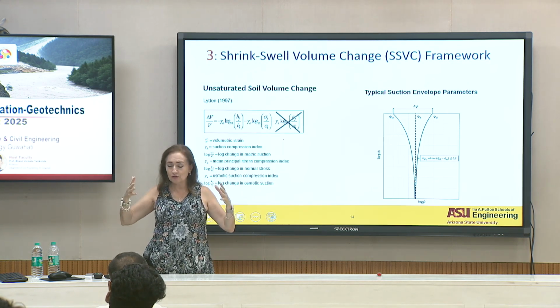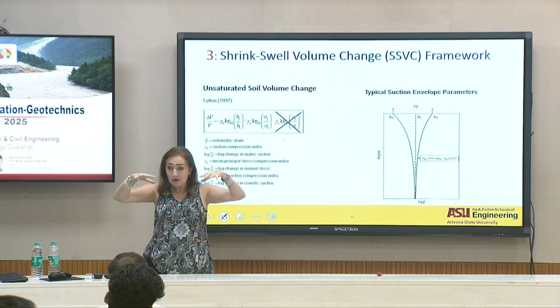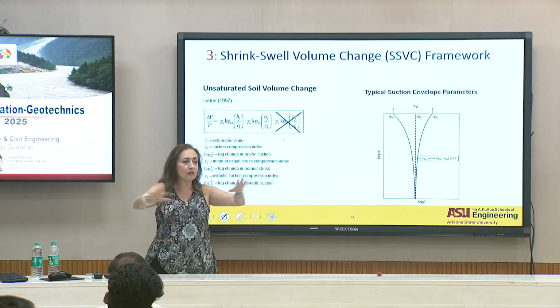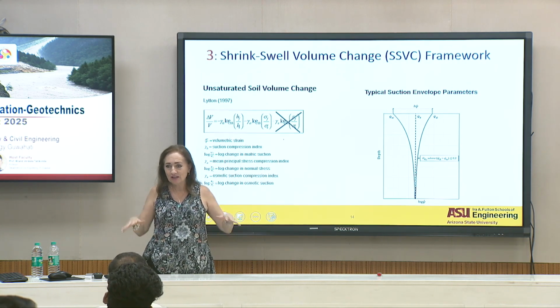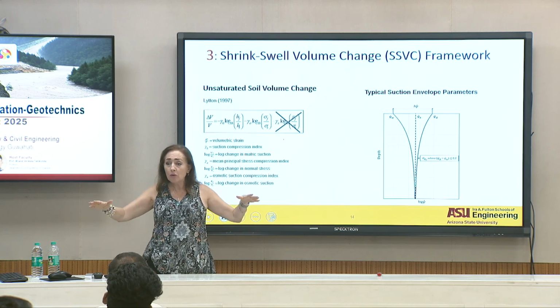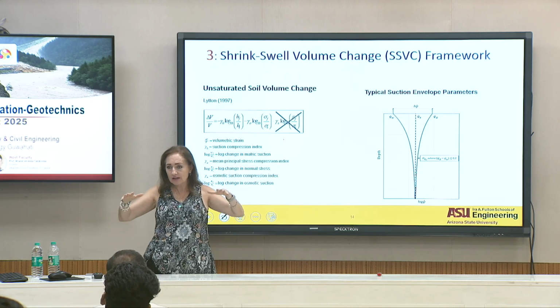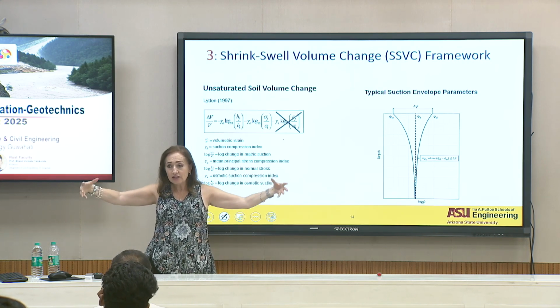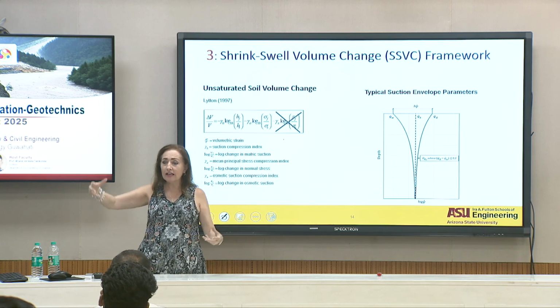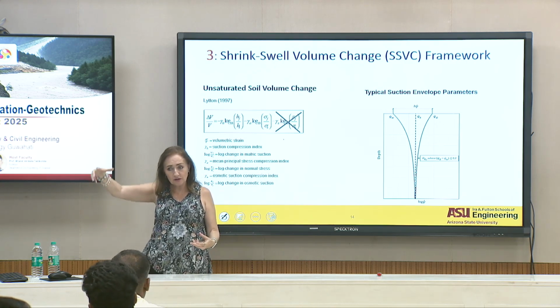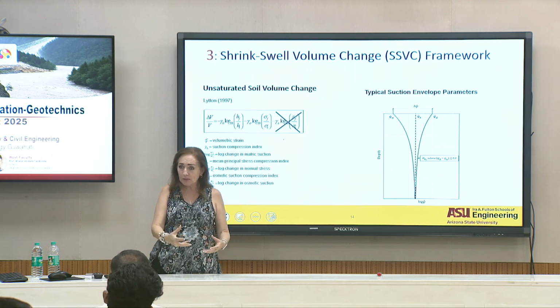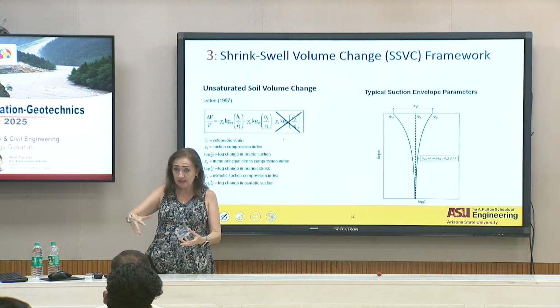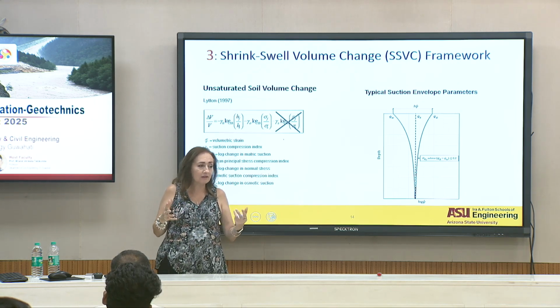And it doesn't depend on whether, because if you have a way to get water in there, which is our problem, right? If everything were paved, then we wouldn't have any problem at all, right? We'd have no water in. But if we do have a way to get the water in, which is usually about the embankments of your pavement, because you have those shoulders. Sometimes you put some gravel in there, sometimes they are open, sometimes they are paved, but then you do have the embankment around, right? This soil is going to tend to the equilibrium value, right? When you have infiltration from rainfall, you get water in below the pavement, and to a point when it starts evaporating, so it's a continuous flux, right? Like we saw on the problem with transient flow.